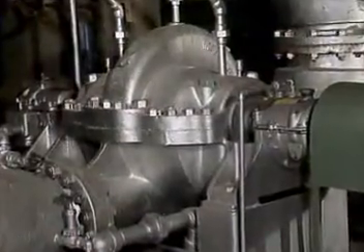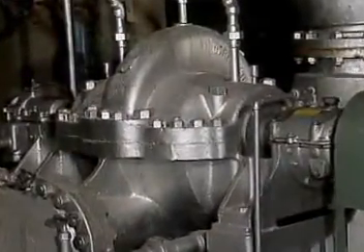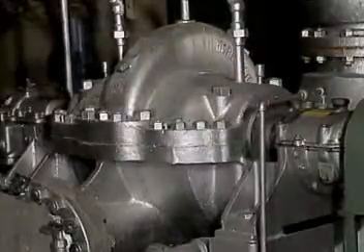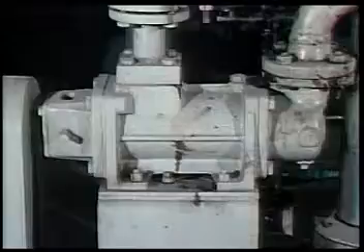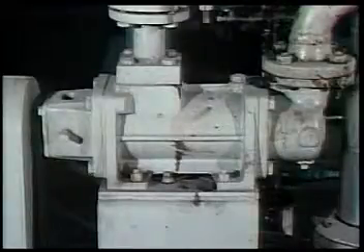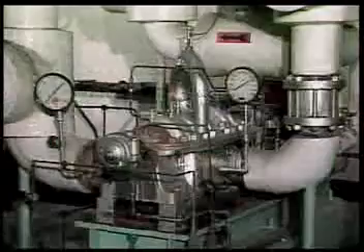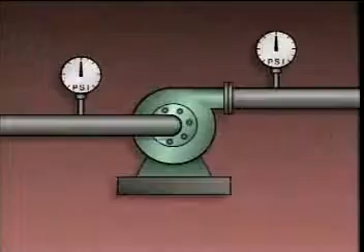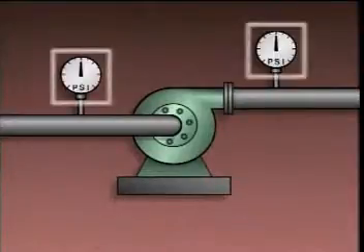liquid system are met. In a liquid system, the energy that's needed to perform a task is often supplied by a pump. A pump adds energy to the liquid and creates flow. 2 types of pumps commonly found in liquid systems are positive displacement pumps and centrifugal pumps. While these pumps operate differently, they both cause flow by creating a pressure difference in the system. Generally, if a pump in a liquid system is not operating, there's no pressure difference in the system, so there's no flow.